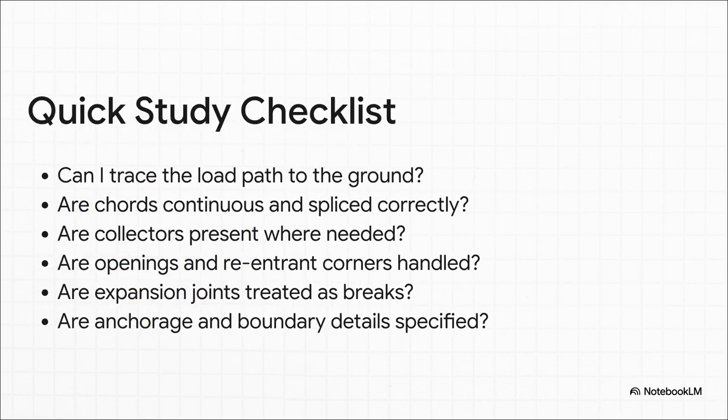So here's your mental checklist. Whenever you're looking at a practice problem, run through these questions. Can I trace the load path? Are the chords continuous? Are collectors where they need to be? How are openings and corners being handled? Is that an expansion joint? Are the boundary details specified? If you can confidently answer all of these, you are in fantastic shape.